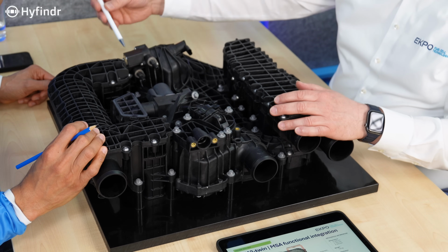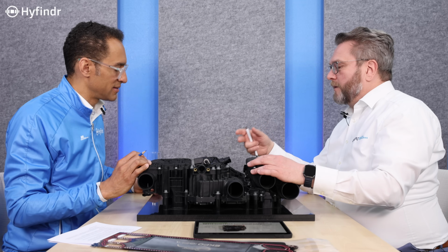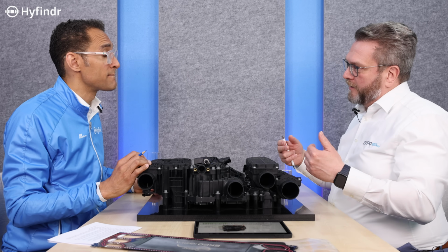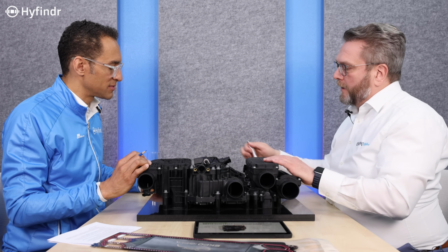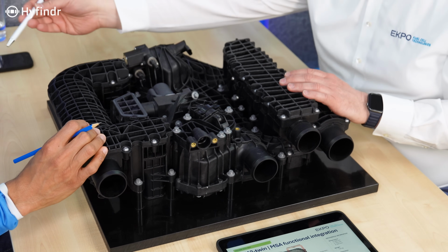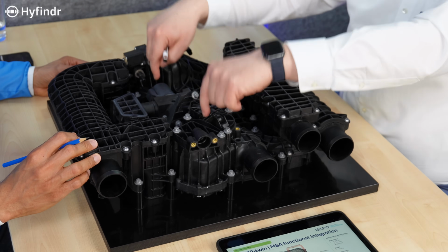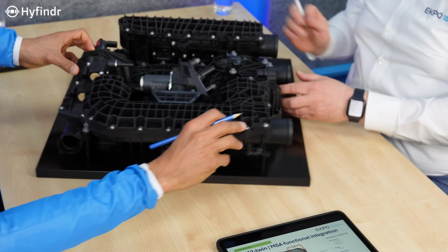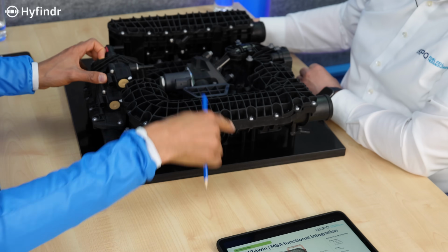And with the second solenoid, we also have the ability to purge the stack. Some nitrogen coming from the air travels through the membrane to the hydrogen side and then accumulates, and we have to remove it. That's why we purge it frequently. The hydrogen coming back from the recirculation pump is then mixed with the fresh hydrogen and goes back into the stack. So basically it comes out here and goes back in there. So this is just the recirculation pump.